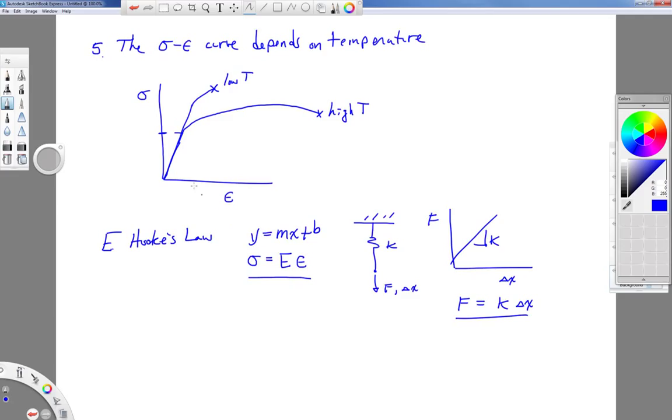Right. So instead of having tables of stress strain curves for different materials, if I know I'm below the proportional limit stress, all I need is a table that has the modulus of elasticity in it and an understanding of this formula. Then I can rearrange this. If I know stress and I want to find strain, I divide it by the modulus of elasticity. If I have strain and I want to find stress, then I multiply it by the modulus of elasticity. We'll do an example here in just a moment. It is important to make note, though, that this equation is only valid for situations when the stress level is less than your proportional limit stress.